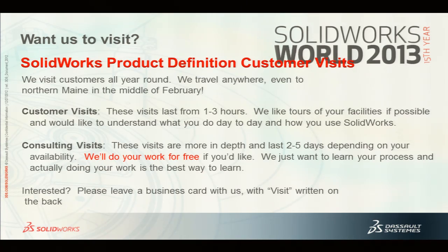The only way you can get that with what I showed is if you have the Scan to 3D add-in, and you also drop down to the file type that says either point cloud or mesh data. Once you open the STL file using one of those file types, then you can do what I do. I can snap to the mesh, I can section it, I can do all those nice things. Okay, does that answer your question?